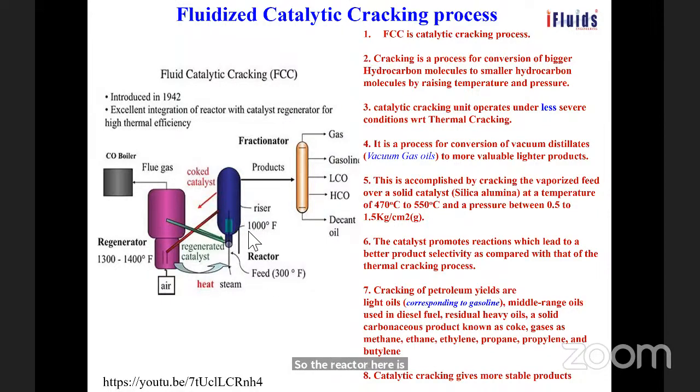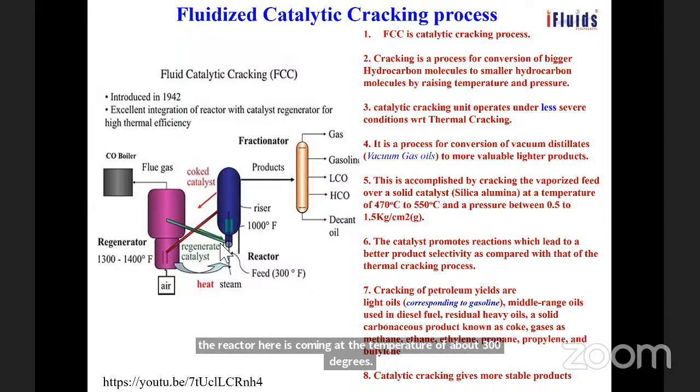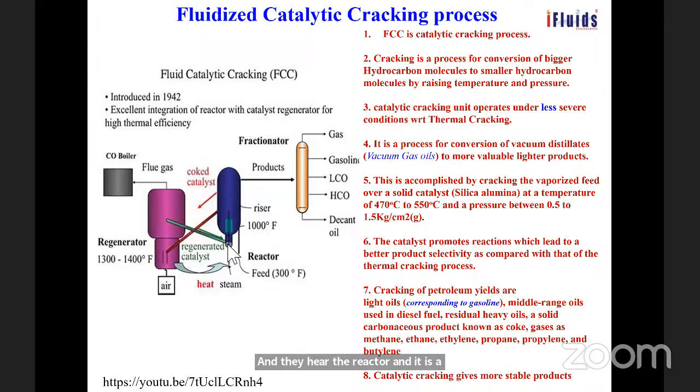In the reactor riser, the catalyst is coming and it is allowed to rise. While it is rising, the feed is allowed to mix with it. So when it goes up, that reaction is getting completed, because there are different variations of this FCC. I'm telling only one particular thing. When it reaches the top of the pipe itself, the reaction is complete. Then the catalyst flows out. Then it starts the circulation. So this is the thing.